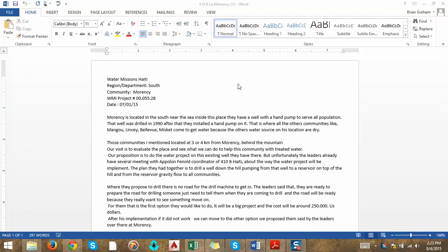Alright, so today I'm going to go through from the start to finish an Abney level survey. Aristeel, our Haitian engineer, went out in the field and took GPS points as well as Abney level data and sent me the GPX files. And I'm going to show you how to take that GPX file, put it into Google Earth, then take that GPX file, extract the points, put them onto Microsoft Excel, and then manipulate those, as well as inputting in some Abney data that will show you a good elevation profile.